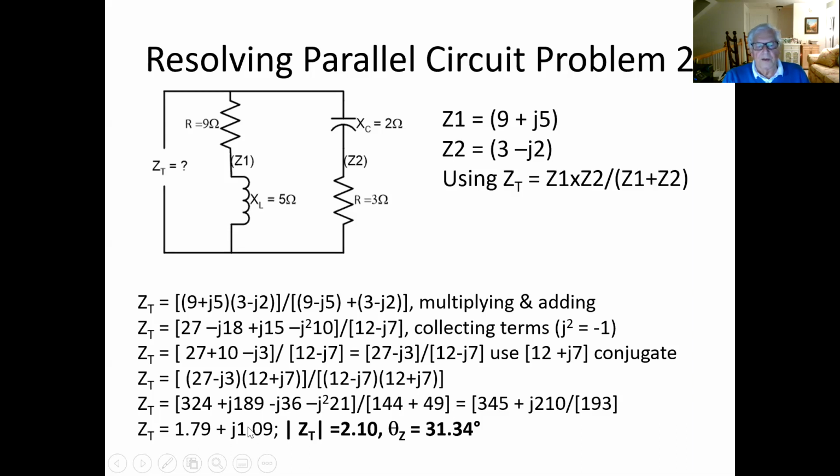Once we apply all of that math, we end up with an answer of 1.79 real plus 1.09 imaginary, giving a magnitude of 2.1 and an angle of 31.34 degrees, meaning it's positive, so it's mostly inductive.